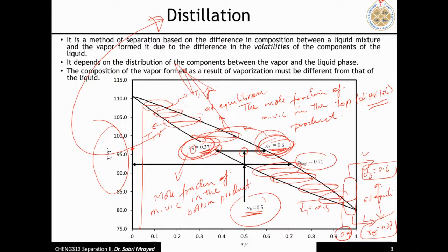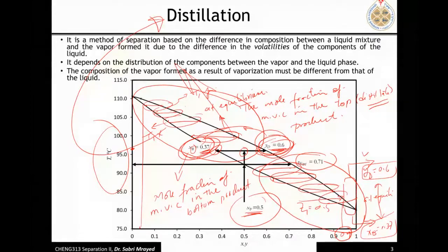So we have cooling taking place, and we have heating taking place. All of the cooling needed in the distillation column will be done by the condenser. Do you remember why we need a condenser? We need to do the cooling because we want to obtain a high purity product. And the heating will be done using the reboiler at the bottom. All of the heating required for all stages will be provided by the reboiler. Okay.